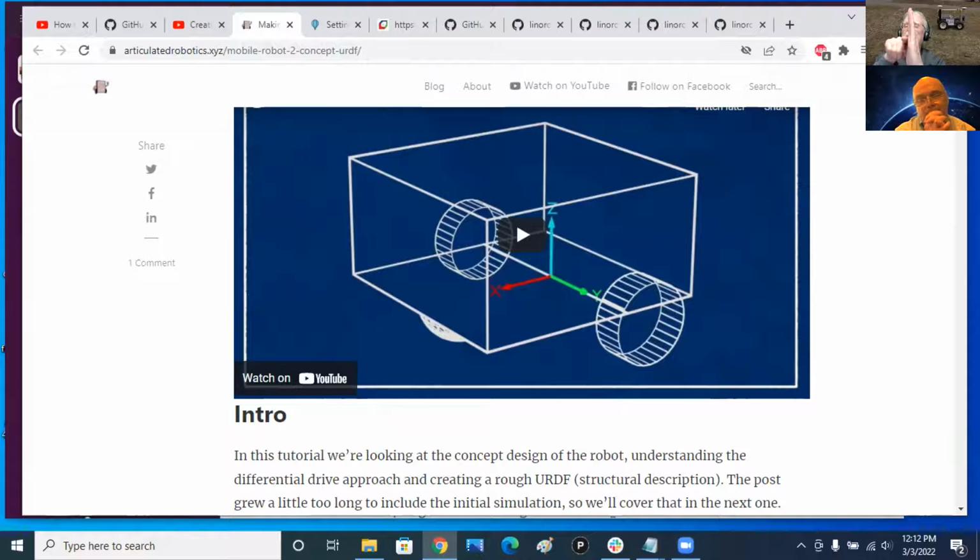And then there's another point where some of the examples I saw, they put the pivot point right in the center of the tire, so it actually rotates around the tire like this. Now, in reality, like on my vehicle that's back behind me there, or on, say, the lawn tractors. Here, let me do this. So you can have a wheel like this, and it pivots right around the center point of the wheel as it steers.